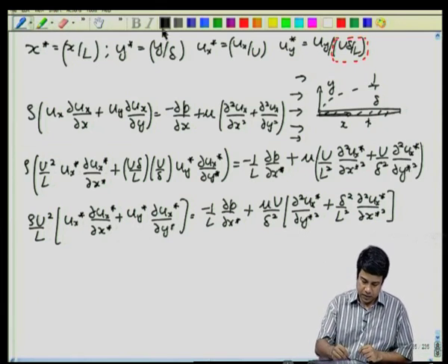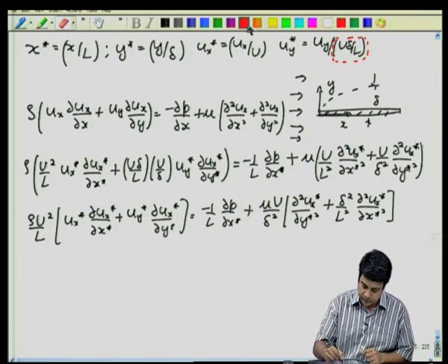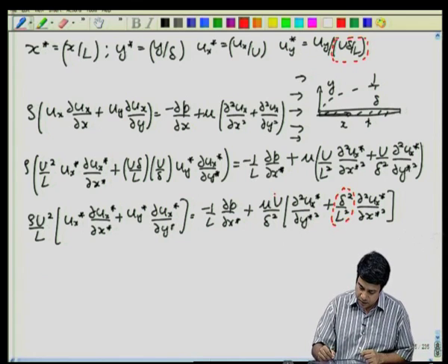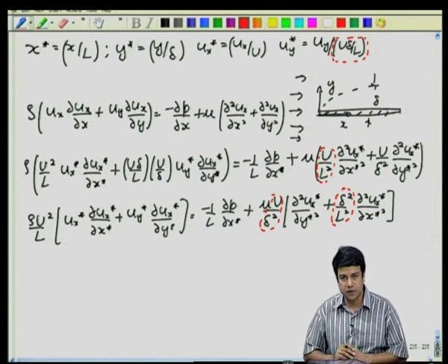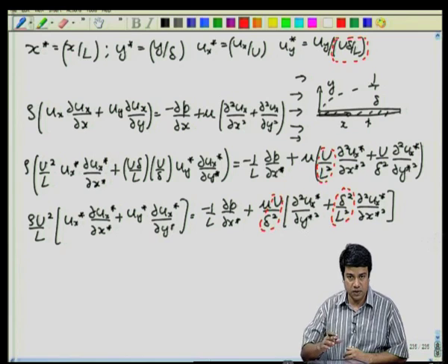You can see that this term multiplied by u by delta square gives me back u by L square, which is the prefactor of partial square u x by partial x square. So, I have just taken one common factor out. I have taken the largest factor as the one in front, because I would expect the largest term to be one that balances the inertial terms.